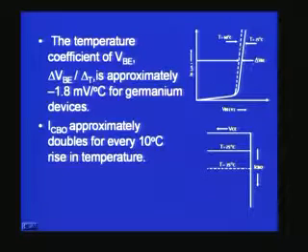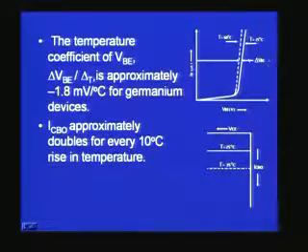As a matter of fact, this variation in VBE with temperature for a constant current can be used as a temperature sensor or a transducer for a thermometer. So there are germanium and silicon thermometers designed based on this principle, that for a given current IC flowing through the diode or the transistor, you can have a continuous variation of about 2 millivolts for every degree, and so if I can amplify and then read it, I will be able to evaluate the temperature. Therefore this can be used as a temperature sensor, which is also one of the applications we can think of.